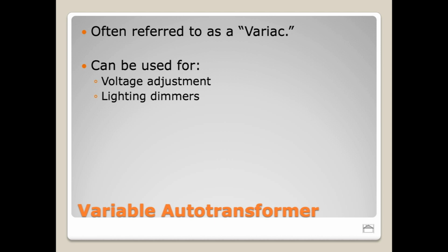If you drop the voltage a little bit below what it's supposed to be, you actually get an interesting tone out of the amplifier. It has a little bit more sloppiness to the tone, right? It's called tube sag, so it just sounds like a softer tone, right? It has a little bit less aggression, less clarity, right? The amplifier's just not running at its full capacity. It's almost kind of like the amplifier's drunk a little bit, right? It's a little bit diminished.